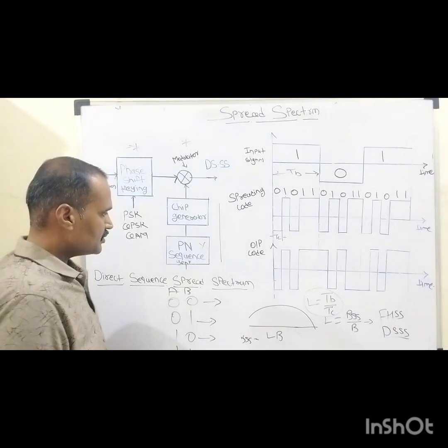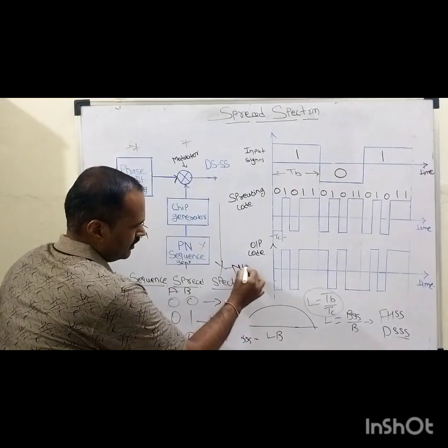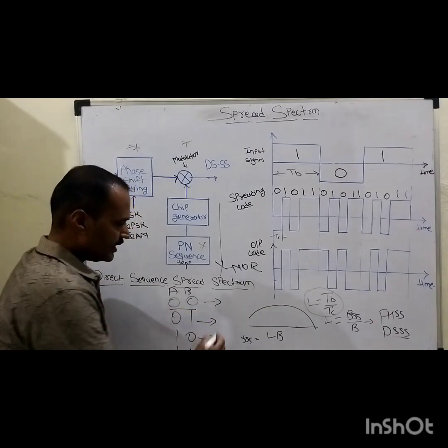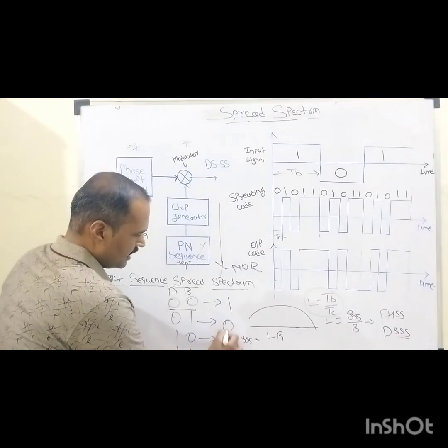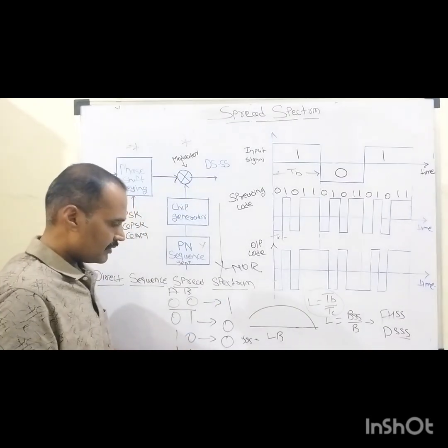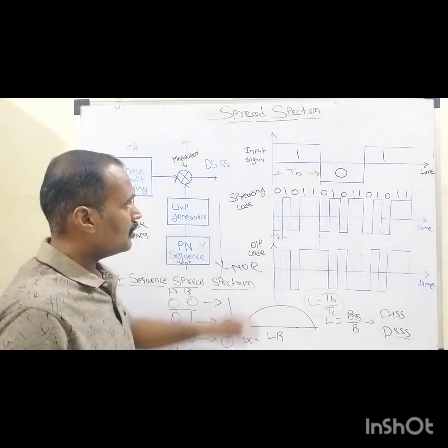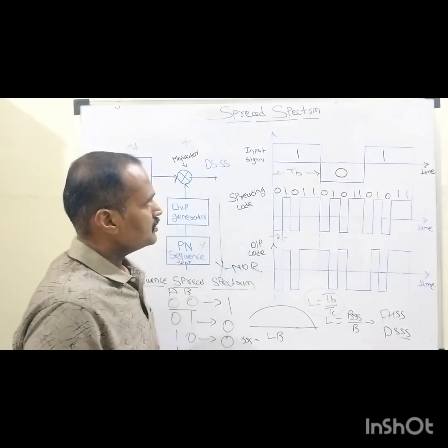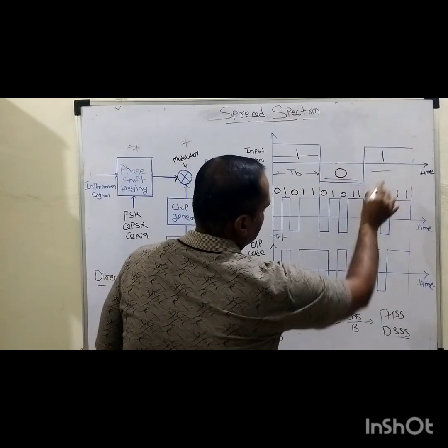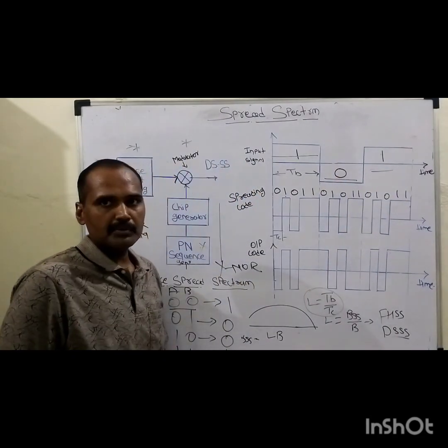As we know, in the XNOR operation, when the two inputs are the same the output is high, otherwise the output is 0. So for 0 0 it is 1 and for 1 1 it is 1. We need to follow that XNOR operation. As you can see here, the first bit is 1, the second is 0, and then the third bit is 1.